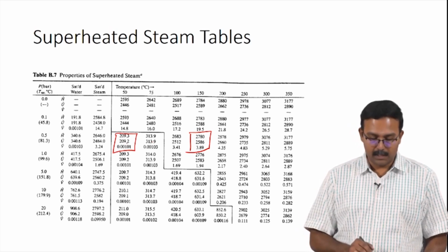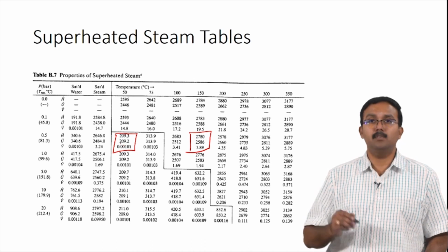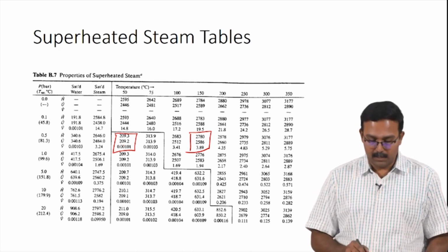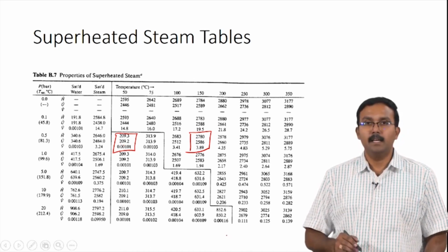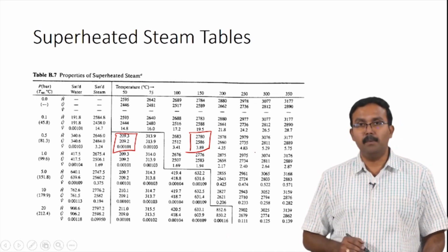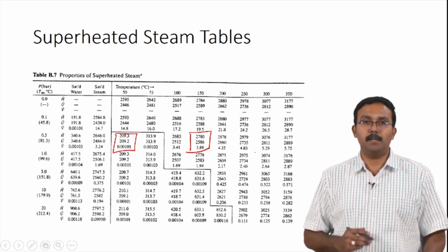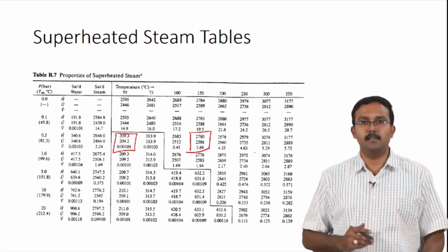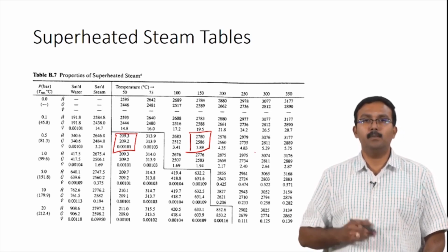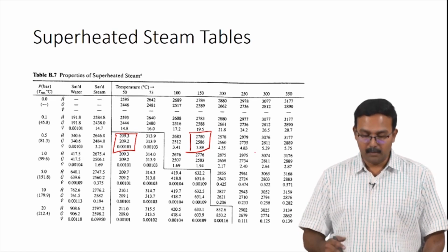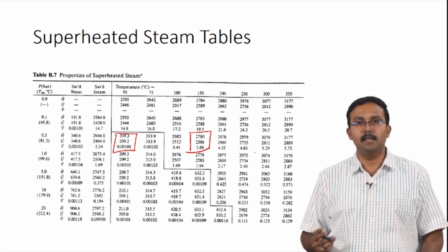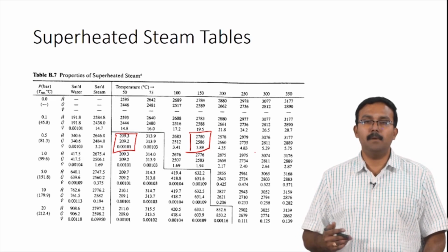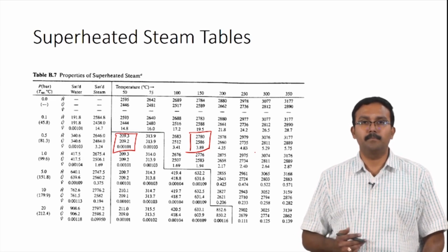So, whatever conditions in which water exists only as liquid is covered within this step shaped box. Everything outside of the step shaped box is a vapor condition. Within the box you have only liquid existing, which is called either a subcooled liquid or liquid, and outside of it is called the superheated steam, where you have only steam and it is not in equilibrium with anything.